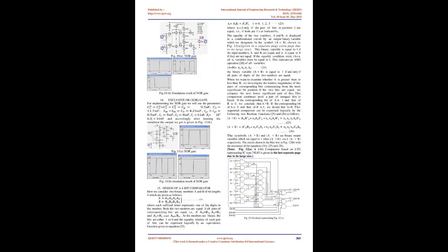equals 0.5, for negatively weighted inputs. Every threshold gate is augmented with an inverter, Fig 1a or 1c. The function of the inverter is to invert/buffer the output of a threshold gate. The logic function done by the buffered threshold gate is the inverse of that done by the threshold gate itself. For instance, a buffered gate implements the function.